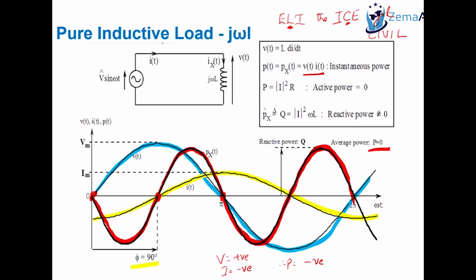Agree? If the transformer core is not magnetized, then the whole transformer action is not going to be there. And what magnetizes the core is actually the reactive current. And same with the motor as well. The motor action, the rotation produced in a motor, is because of the inductance and the phase shift that it introduces, and therefore the angle between the two forces that result in a rotation.